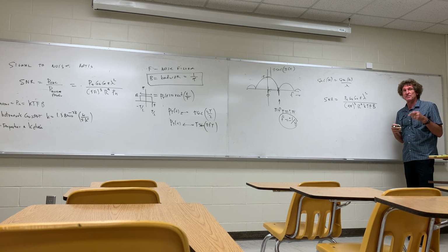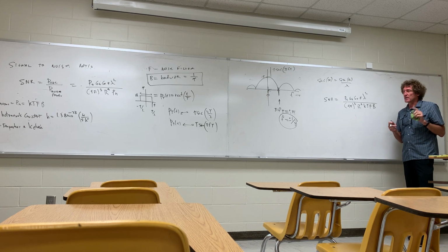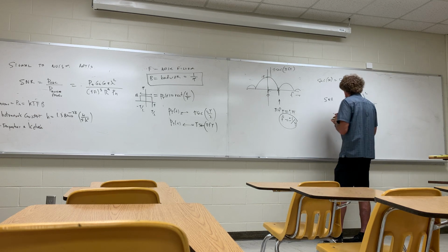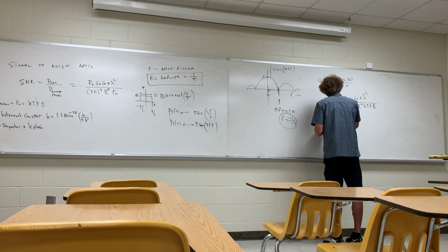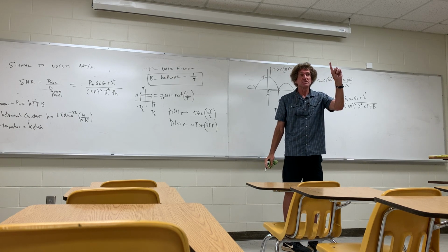And that's the standard form for signal to noise ratio for a radar. And by the way, this is a figure of merit. It tells the goodness of the radar. The higher the signal to noise ratio for the worst case target scenario, the better the radar is. Gotta say one more thing too. That was the signal to noise ratio for one pulse.